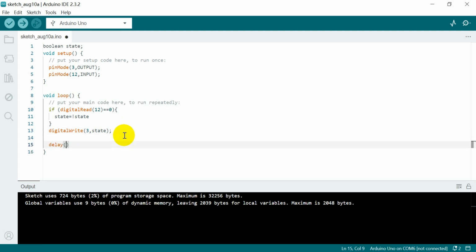And then let's add a line so that if you hold the LED, it does nothing. It doesn't flicker on and off really fast. That's what this line is for. And then the delay, before and after the while loop, is for the static. So when you press the button, it's not a perfect on and off. There's a time in between that is on and off at the same time, and that's about 20 milliseconds. So like this. This should work. Let's not forget the semicolon here.